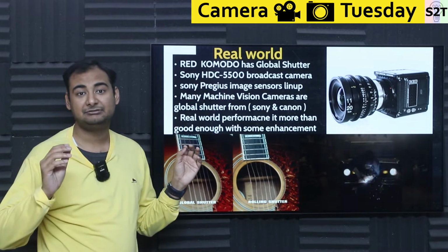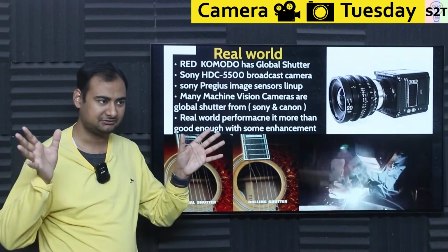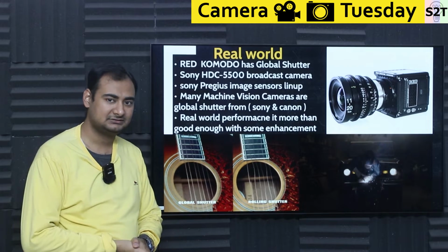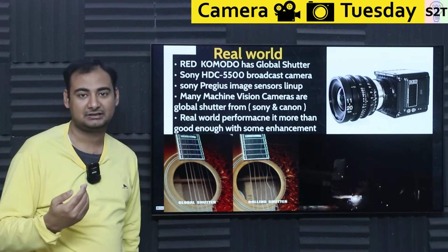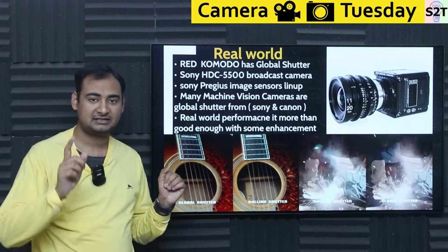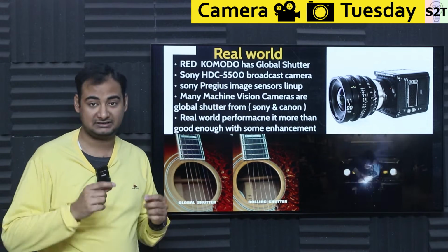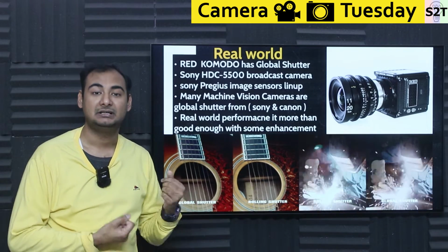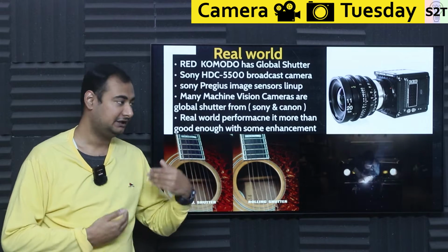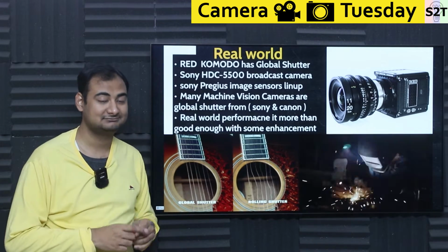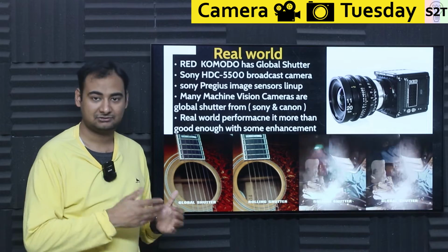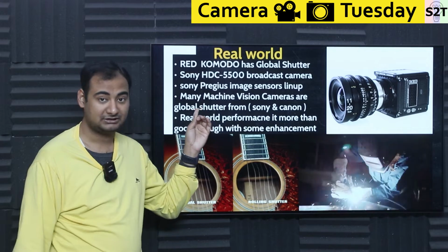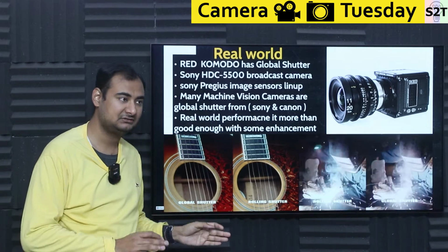And if you are ever wondering how the heck police cameras can scan number plates, when you try to do it all you get is a smeary mess, because motion has a rolling shutter. How do police cameras do it? Global shutter. If you ever hear about a Sony sensor, Sony sensors have multiple series. The Sony Pregius series is an image chip lineup which has global shutter. Meaning if I want to build, let's say, a security camera, I buy global shutter. If I want to build a dash cam, it requires global shutter, because without it, all it does is a smeary mess if I try to read the number plate. So you can use Sony Pregius, and many machine vision systems are already using it.